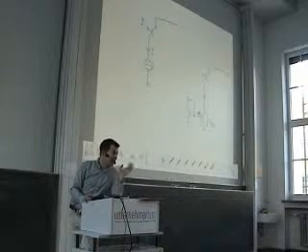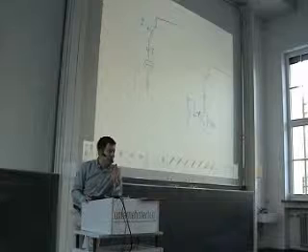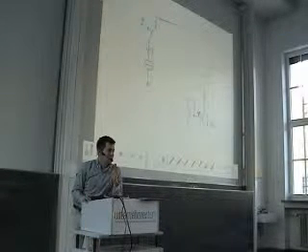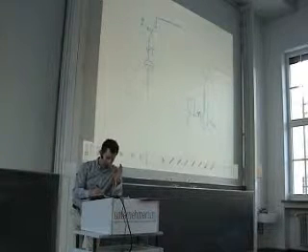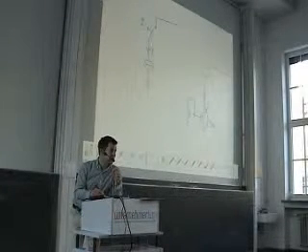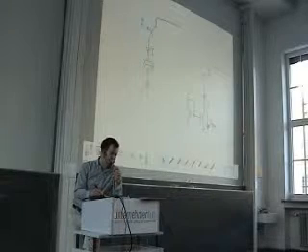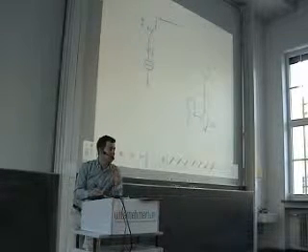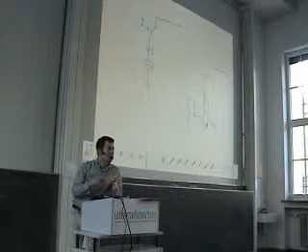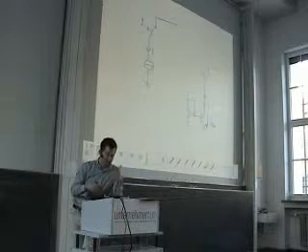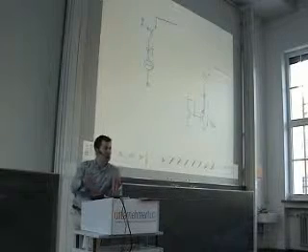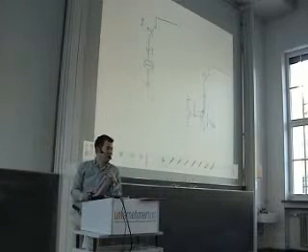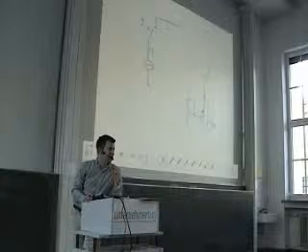Well, it would be possible, but then if I connect the switch back and want the device again to work as a current source, then first I have to bring up this voltage, and first I have to bring this device into saturation, which consumes a considerable amount of time and also causes transients, because at the beginning the current is 0, then it comes up, so everything settles very slowly in the DAC.